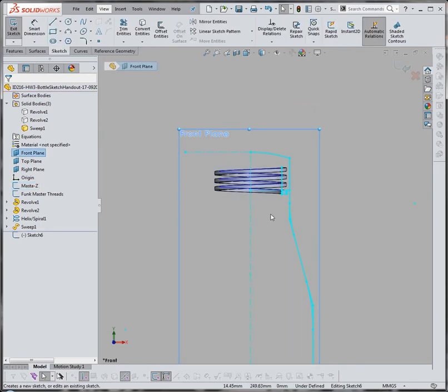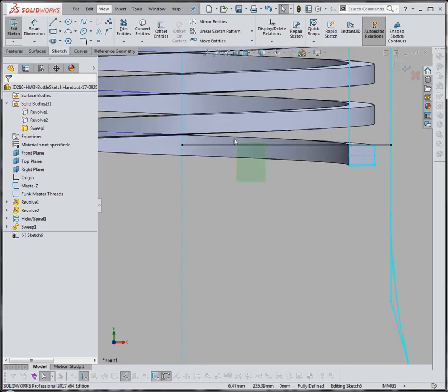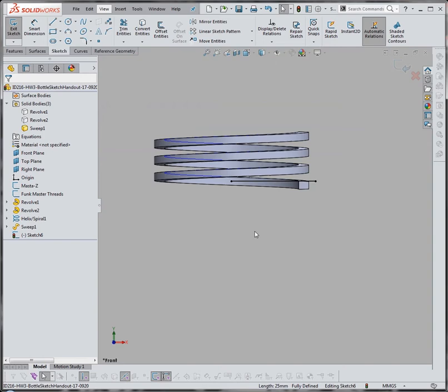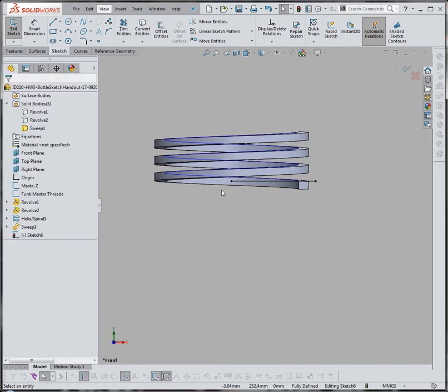So, creating yet another new sketch on the front plane, I will convert that horizontal line. You may have just noticed this, but when I convert construction geometry, it comes through as a regular full-blooded line. If I really want it to be construction geometry, I could select it again and hit for construction, but that's fine because I actually do want it to be a real line.